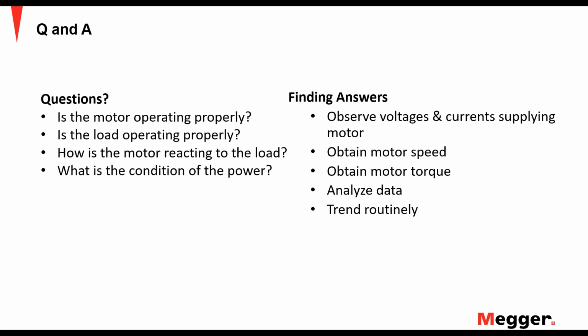If I have a rock crusher, its loading, its torque ripple, its instantaneous torque, what's coming through that air gap, is going to be very different than that of a smooth running pump. As a rock crusher hits rock and crushes it, you're going to have a lot of swing in that torque, whereas with a smooth running pump, it'd be very smooth.